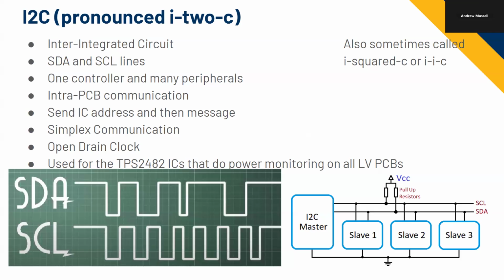Yeah. What's typically causing the noise just in general with these communication networks? Yeah, I mean, there's a bunch of stuff. There's external sources, like the grid is 60 hertz. Sometimes you'll just be looking at your oscilloscope, and I had a really bad laptop power supply once and I was probing a board next to it and you'll just see 60 hertz get picked up on your oscilloscope probe because the power supply is switching at 60 hertz to take grid power and put it into your laptop.